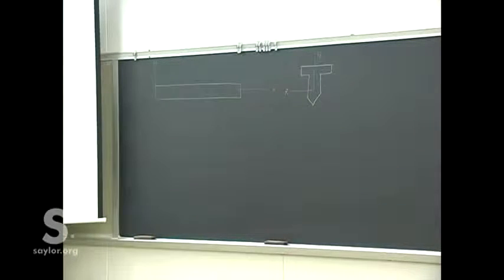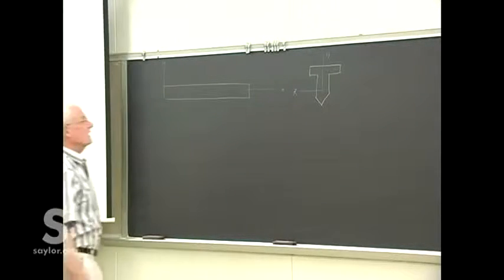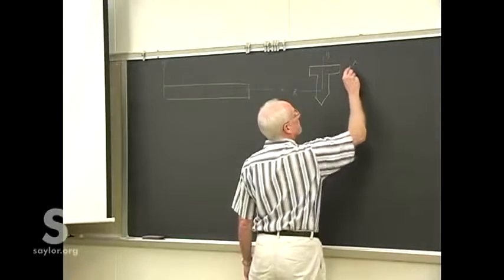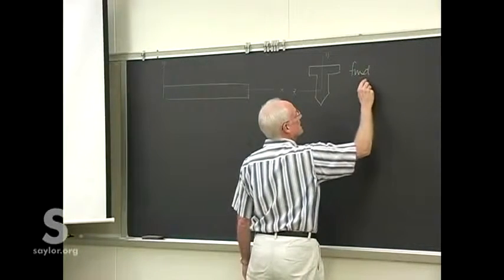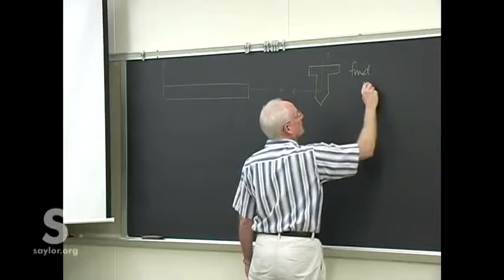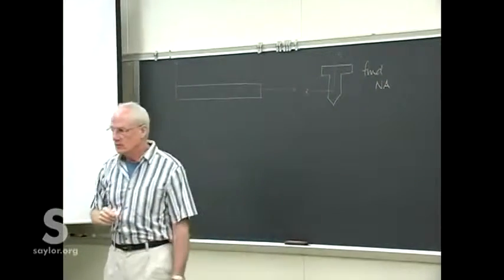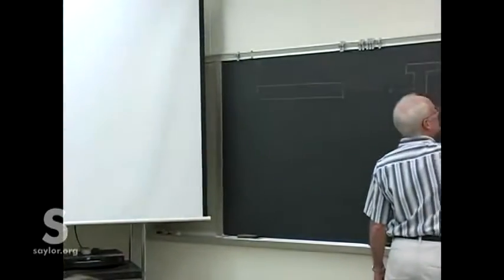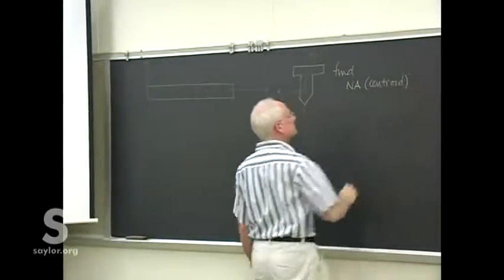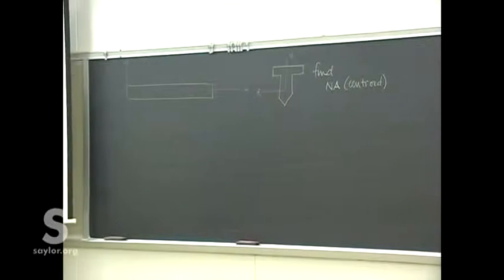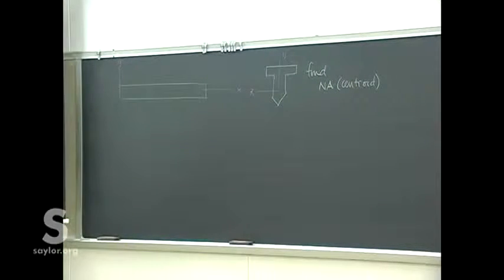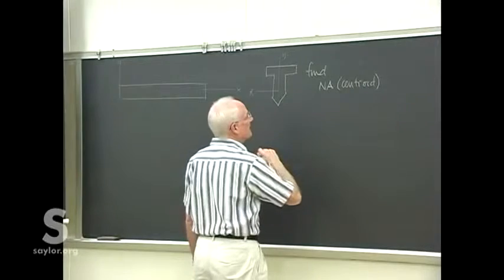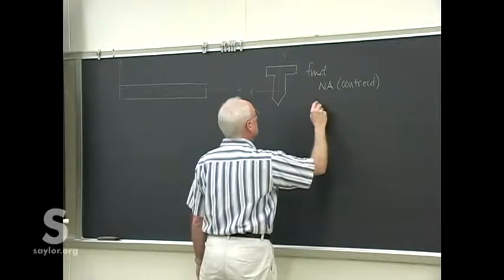And then the only other part of the concern with that is, if you remember, we need to find two things with this cross-section now. We need to find what we call the neutral axis, and we'll review in a second why we need that, but it turns out it goes through the area centroid anyway, so it's just a matter of finding the centroid of that area. And then from there, then we can find the bending,